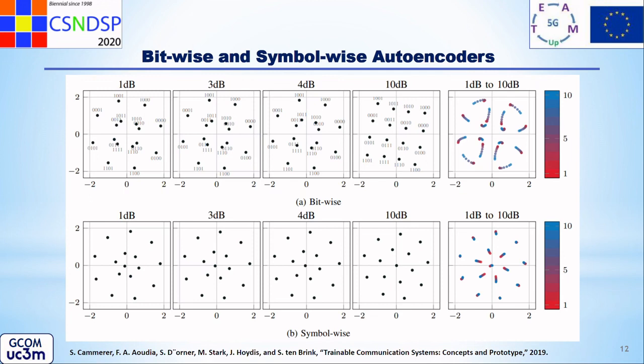In the bitwise case, from left to right, we go from least important bit to most important bit. Therefore, one can check that the symbols are placed so that the ones differing in bits more on the right are at a higher distance, while those differing in bits more on the left are closer to each other.